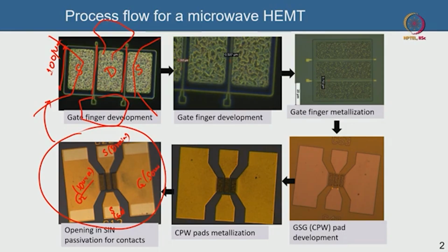Now why am I showing you this? It is because at the heart of it we are talking about RF signals, which are electromagnetic signals, and we are making them propagate in a semiconductor wafer, inside all these metal structures or inside the semiconductor substrate itself. So what we have to talk about are things like transmission lines or waveguides, because the electromagnetic wave, which is the RF signal, is going to propagate through these structures. We call this particular GSG structure a coplanar waveguide, CPW,